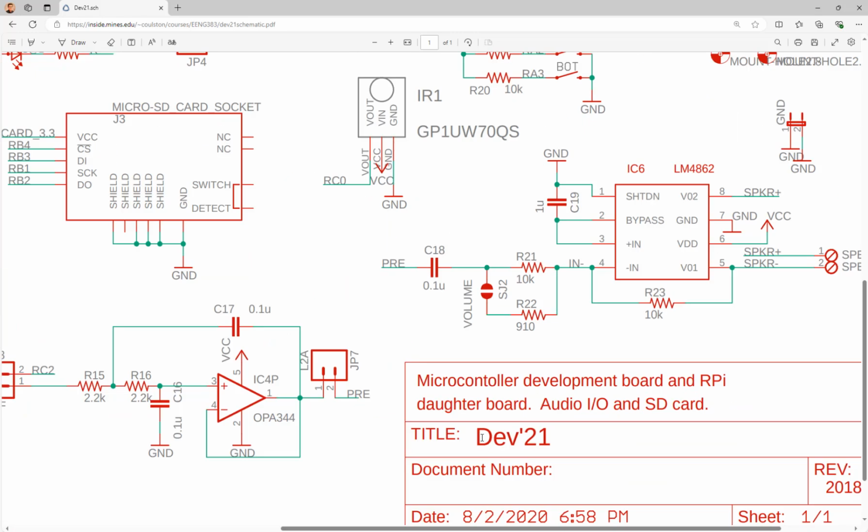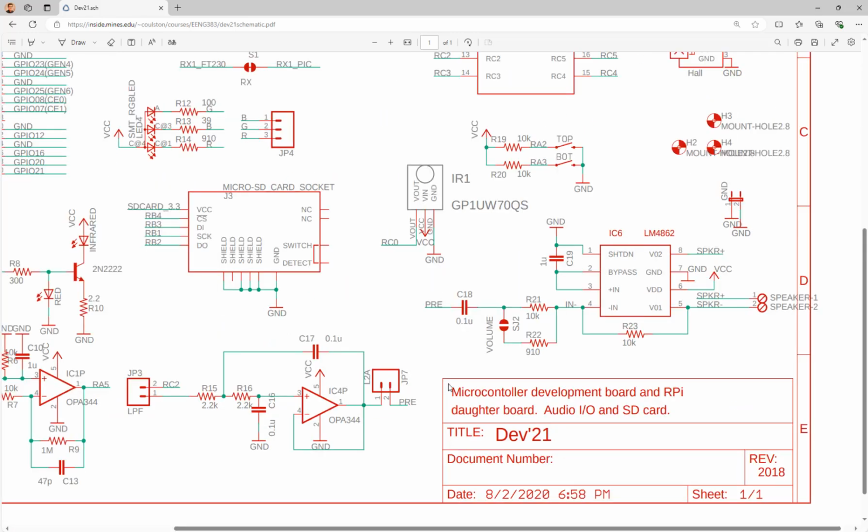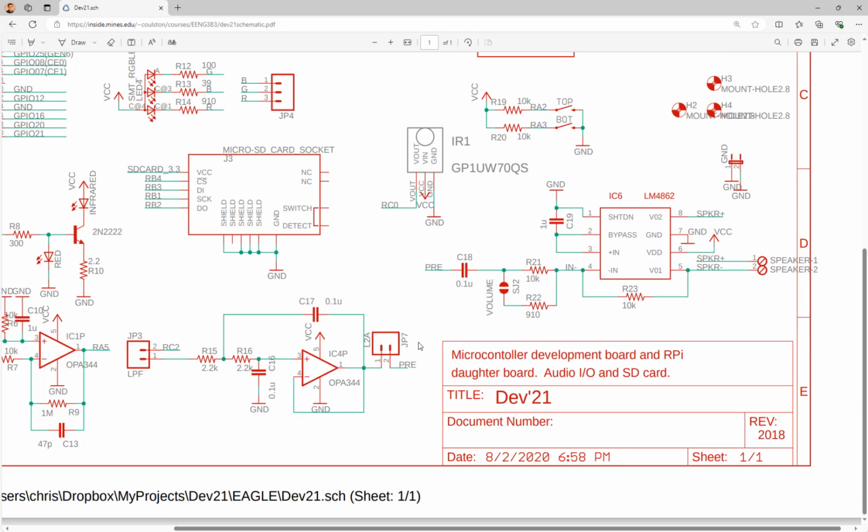What's really happening here is on the PCB, you'll see on the right-hand side of the layout, there's a little jumper header that if you plug in the header, it's shorting here to here. Okay? This is the audio amplifier. This is another high-pass filter outside of the audio amplifier. And this is a low-pass filter, and that's the output. That's the input. If you see, they have the same name, so it means they are electrically shorted. This is the jumper.